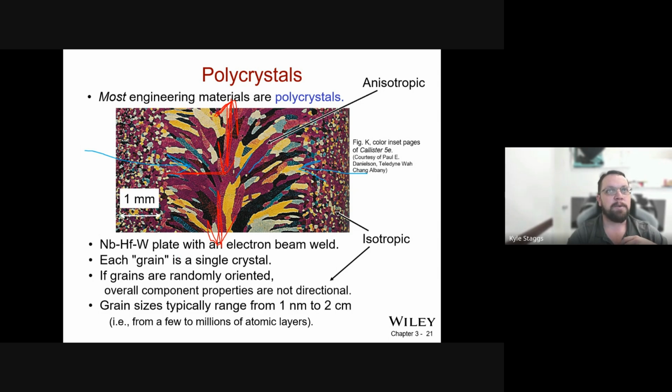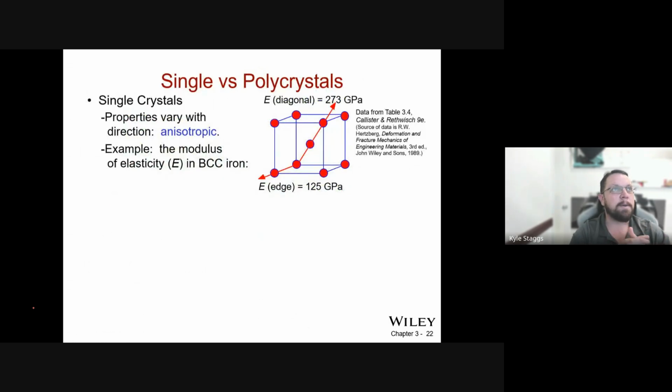But if you change directions and you start to try and pull away right here at the edges, that difference in size of grains is going to create a weakness in these materials. And so it's going to yield much more easily in that direction. And that's why that mechanism happens the way that it does. So hopefully that clarifies at least a little bit of what we're talking about there.